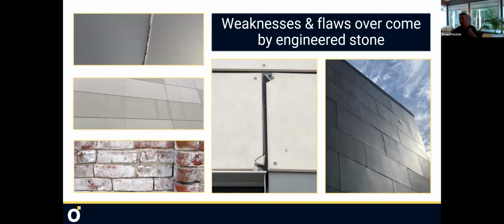What will that do? Well, if something's wet next to something dry and pollen comes through, the wet will attract the pollen and hold it there. The pollen will then turn from green to black as it rots, and you will get staining in the form of ghosting. So even though it's wet, you'll say, well, it'll just dry out. And that's fine, and it may, but not before over time, those areas will attract more discoloration as a result of their hydrothermal inefficiencies.